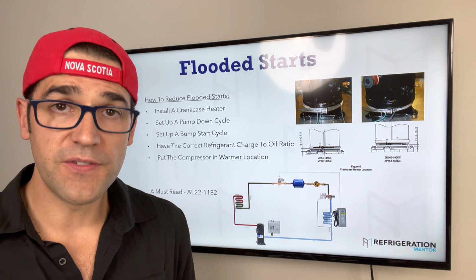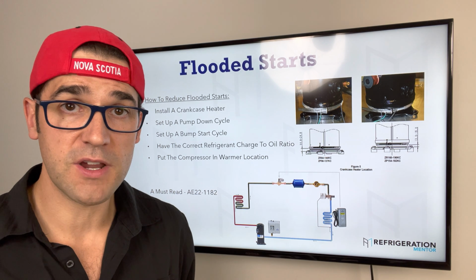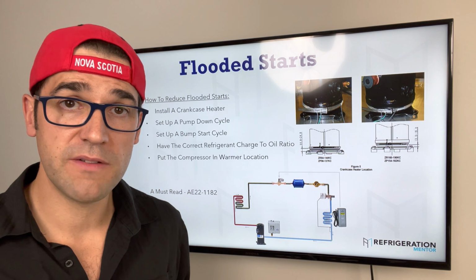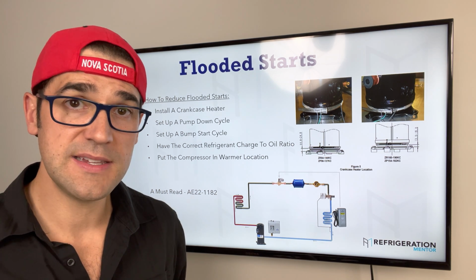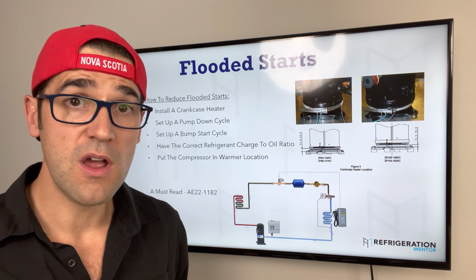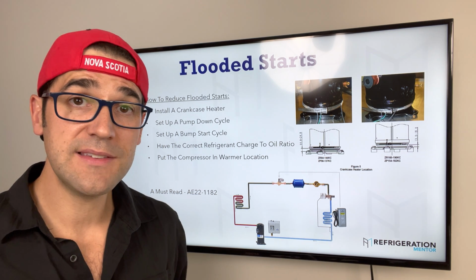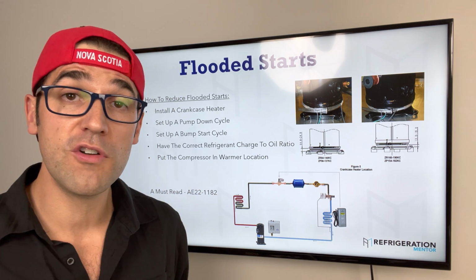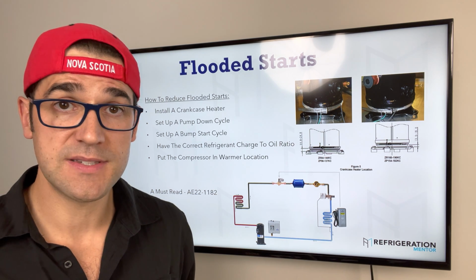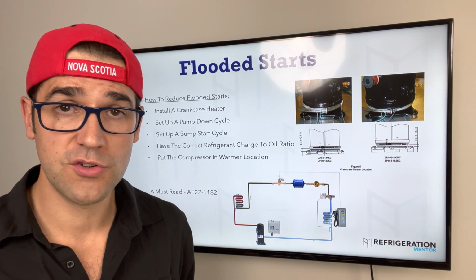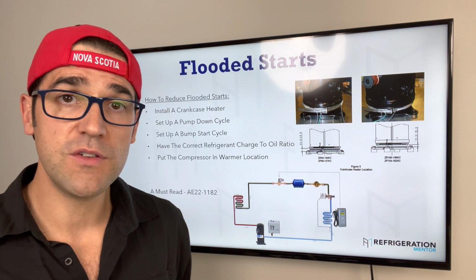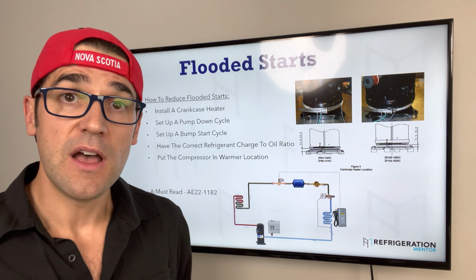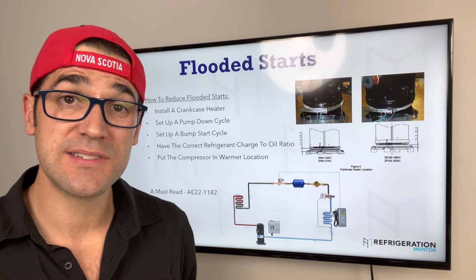So once again, flooded starts is caused by refrigerant migration. That refrigerant migrates into the compressor. That compressor starts up and has an explosion of liquid refrigerant, washes oil away to cause seized compressor, broken parts like pistons and rods or scroll sets themselves. Things to prevent it: adding a crankcase heater, checking they're in the right location, checking if they're even working or they're the right wattages. Having a pump down scenario, setting it up properly, setting that low pressure control up correctly, making sure that if you need a discharge check valve in the discharge line, that you add that one or have that one there. Accumulators do not protect against flooded starts.